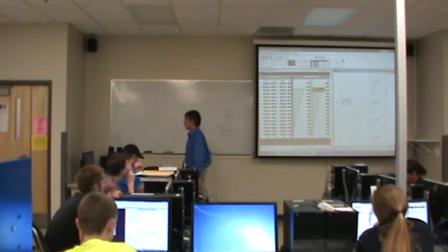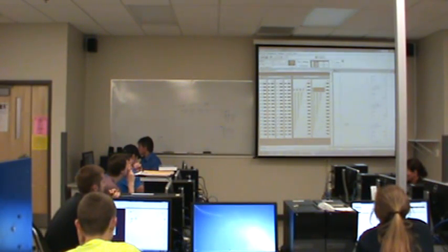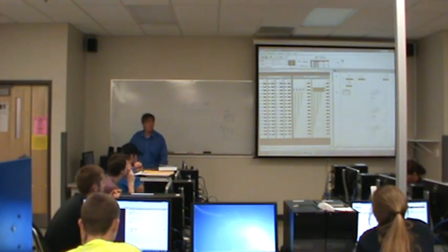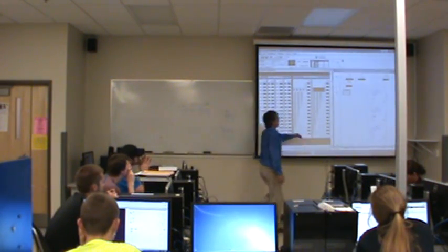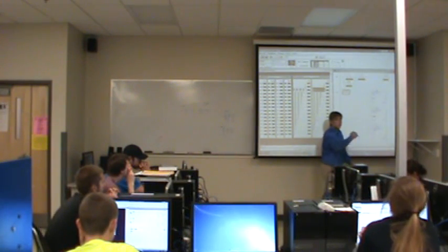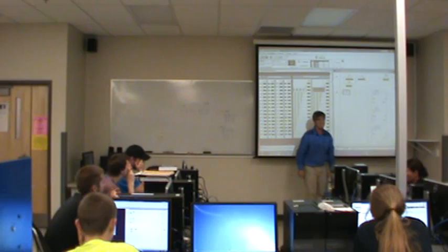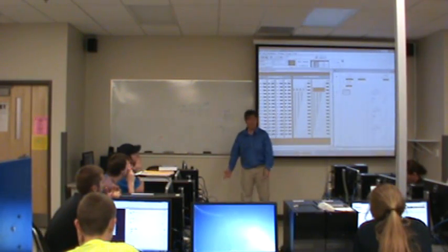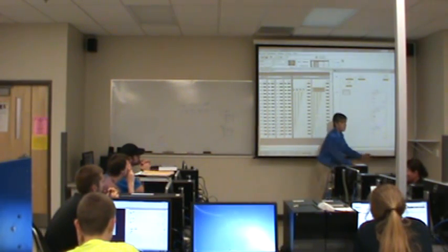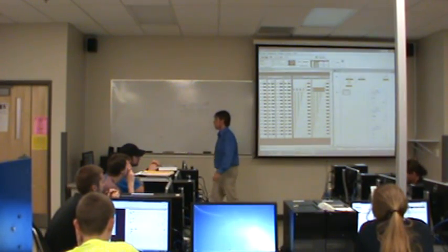So I put that in front of both sets of instructions. Notice I had to reference two different bits. If I reference the same bit, what would happen is it would come to this line, the PLC would see that this bit is off, it would turn the bit on and perform this. Then it would go to the next line, and if I use this same bit, it would see the bit's on and not do anything. Now another way to get around that is I could have put more ORs and put all the input stuff on the same line, but I was trying to keep them separate.